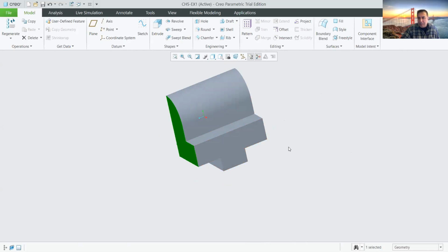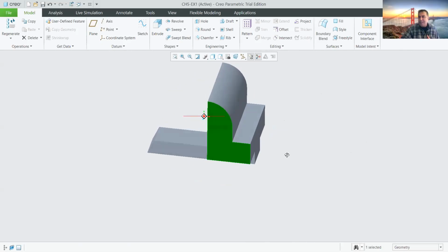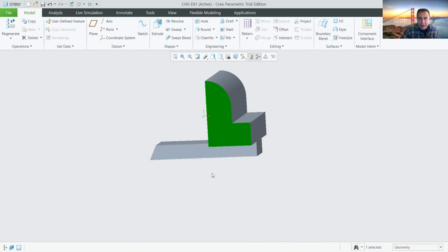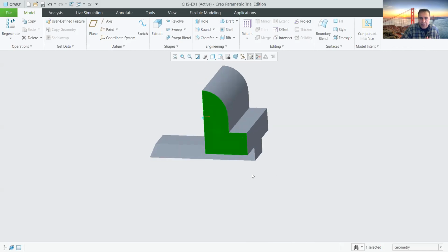Let me just clarify something in mechanical drawing or any type of engineering graphics, communications, or the solid model we're creating. Please remember that in the US system of drafting, if we are looking at the front view, the front view has the dimensions called width and height, okay? There is no length. It's not like a mathematics algebra rectangle with a length and width. Please remember that we don't use the language of length here. We say width, this is the width, and this is the height.